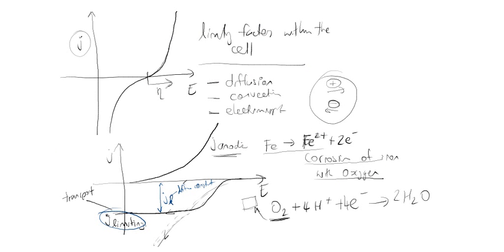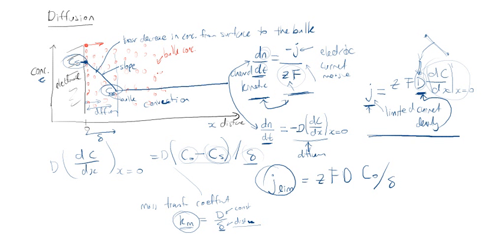say that this here is our limiting current for this reaction. So if we're thinking about the breakdown or the corrosion of iron, what we want to do is make this value here as small as possible, right? We want to limit the amount of corrosion that occurs on this electrode surface as much as possible. And so we're going to be considering how we can change our mass transfer coefficient, how we can maybe increase the diffusion layer distance, and that will actually slow down the corrosion.